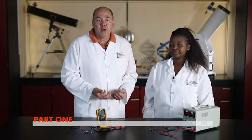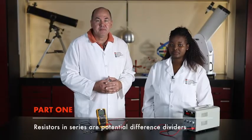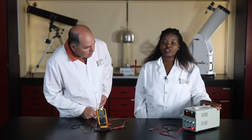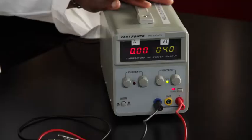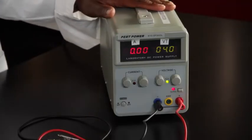Welcome back again. We're working through part 1, resistors in series. Instead of using a battery, today we're using a power pack, which gives us steady potential difference all the time. We're doing this so that we eliminate any effects of internal resistance in a battery. Batteries can be fresh or they can be well used and so out of energy that they are flat. We want to avoid these effects. So today we are using this power pack to provide a reliable and steady potential difference across our circuit at all times.